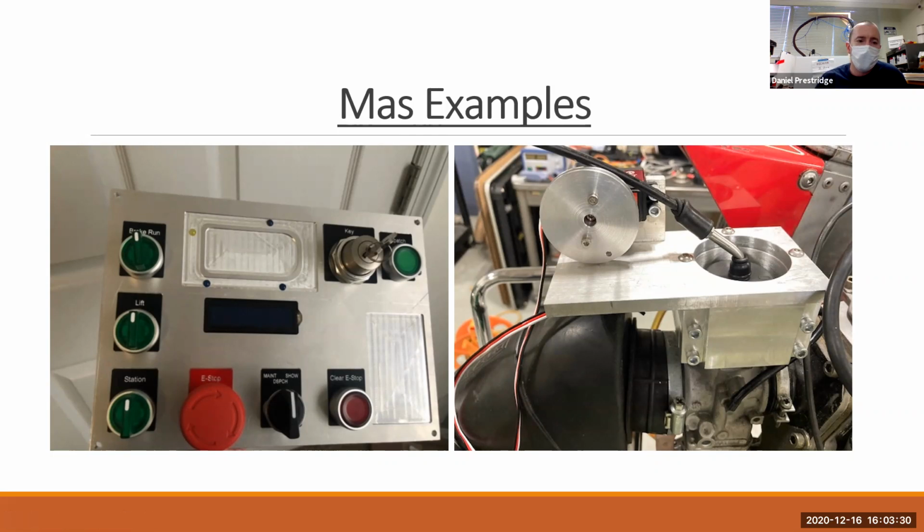So let's say that there was a 3.5 millimeter tap hole for this corner to mount something. And then the rest of it was a ton of material that you're clearing out. Like let's say the whole middle part of this was all cleared out, which underneath these buttons, it is cleared out. They put it all in there. So we're not gonna take the little itty bitty end mill from here and try to do all of the rest of this stuff because it would take absolutely forever.